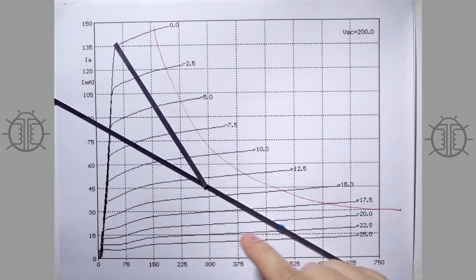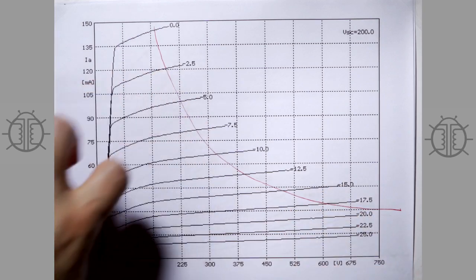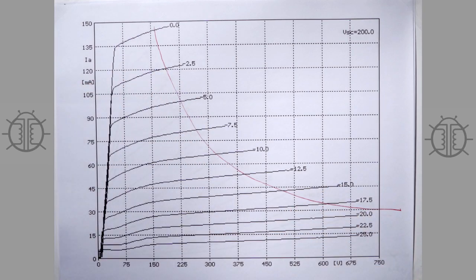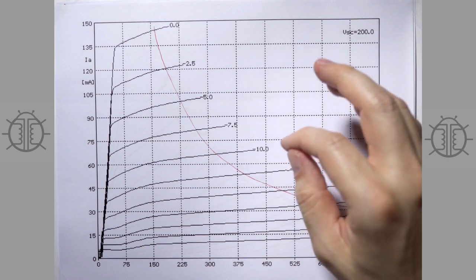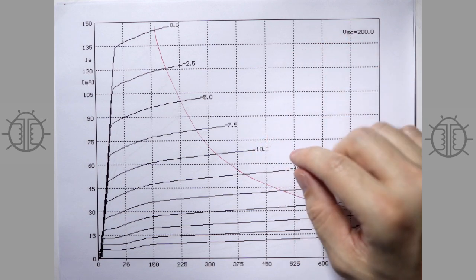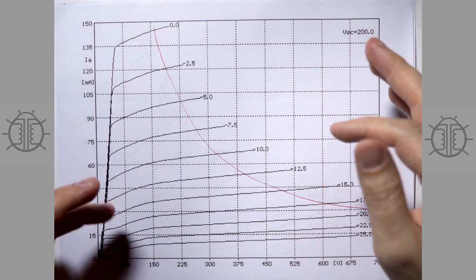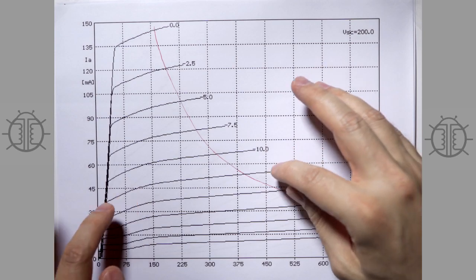But let's talk about these pentode curves and talk about plate impedance. Now before we went up from like 1.8 to 2.4K or something like that. But if you look at the plate impedance of a pentode, it's very much higher than that. So let's say I'd like to change the voltage of the plate by, what is this here?